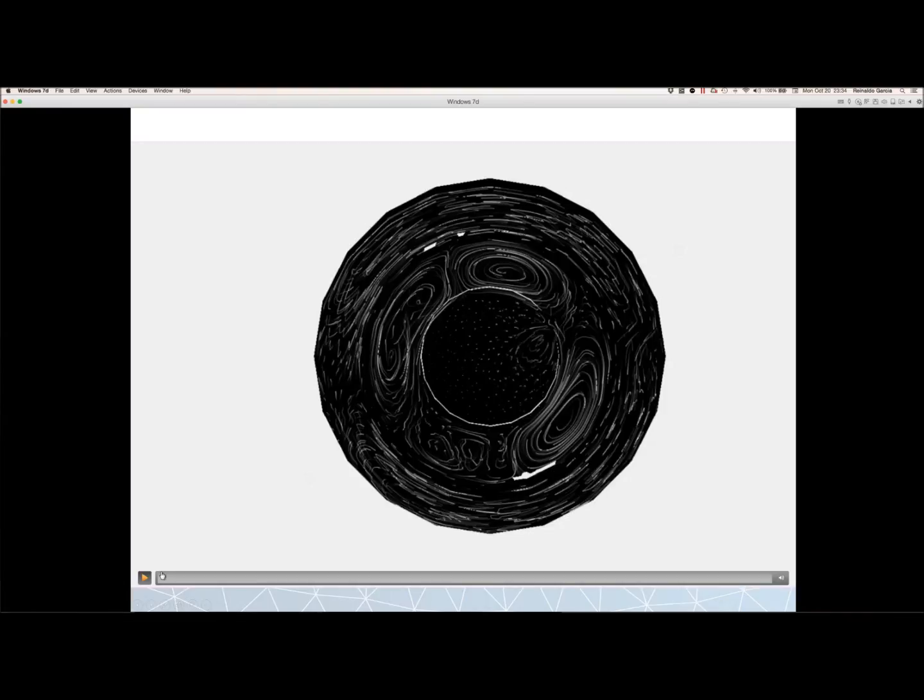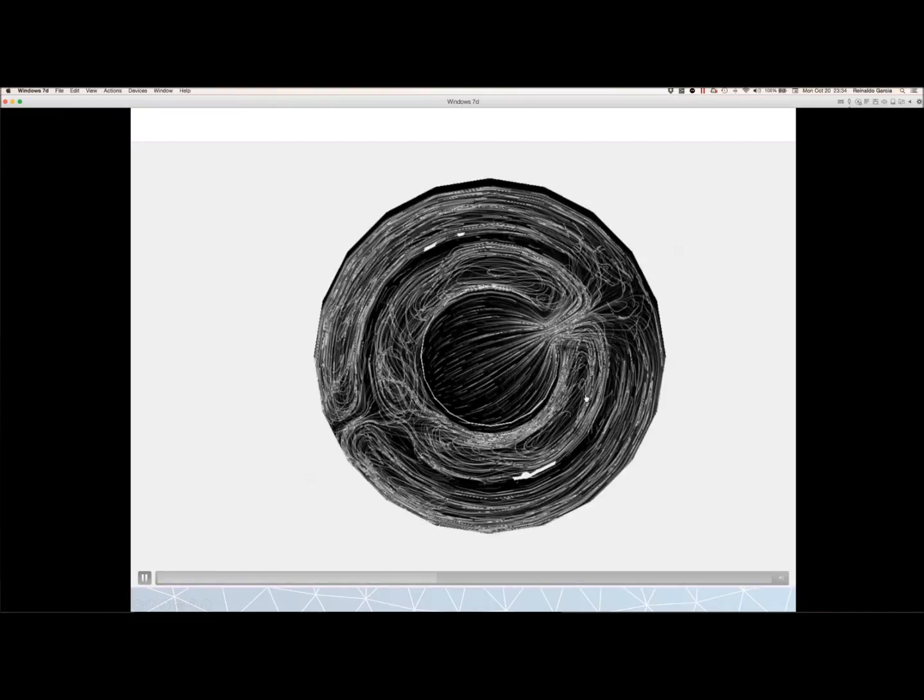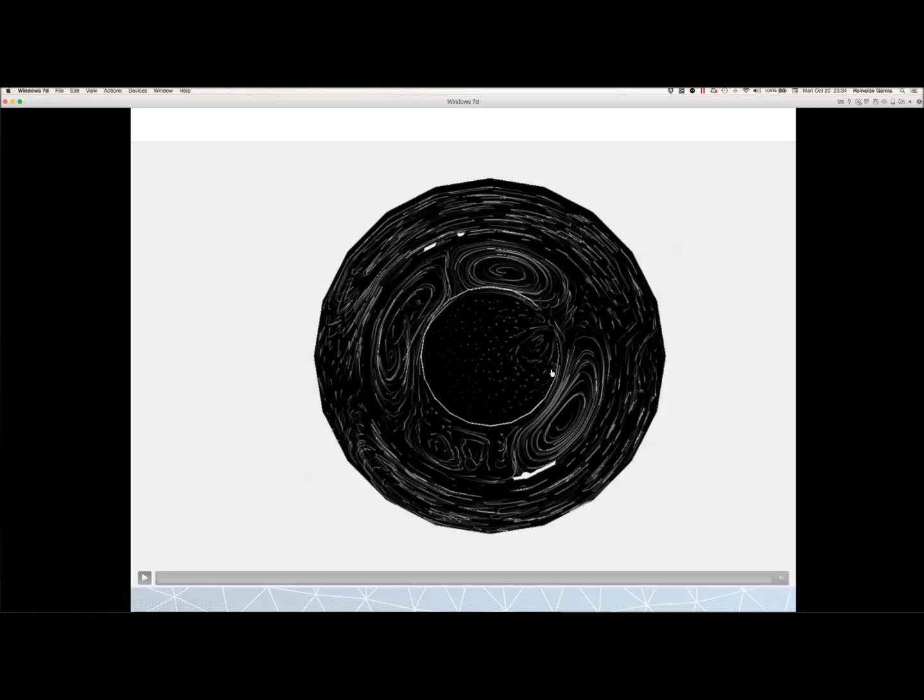So you see the eddies that occur here in between the embankment and the tank. With a model like OilFlow2D, you can get a lot of detail that is normally not available with a different type of model. The flexible mesh allows you to refine and adapt very well to these curved surfaces. If you had a model that uses square elements, for example, you cannot resolve areas like this very easily.